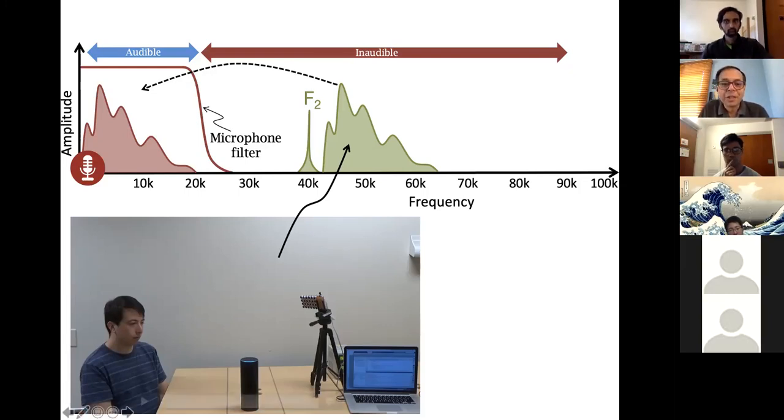So I showed you the ideal view. In reality, what also happens is each of these green mountains has a bunch of frequencies, right? They will also interact with each other. So you will see other signals in addition to the red signal over here, right? But remember, the gap between those frequency signals is smaller, right? So they are not going to span the same way as the red mountain. They are going to span a smaller bandwidth. Very good question. So it is going to affect it. The quality of the recorded signal is not going to be great, but it will clearly be audible.